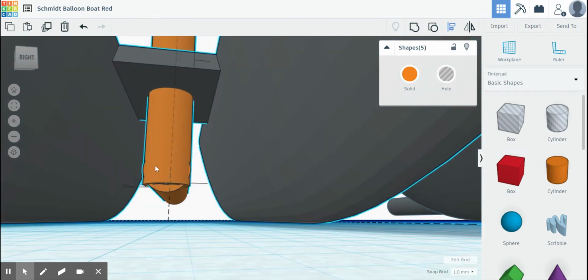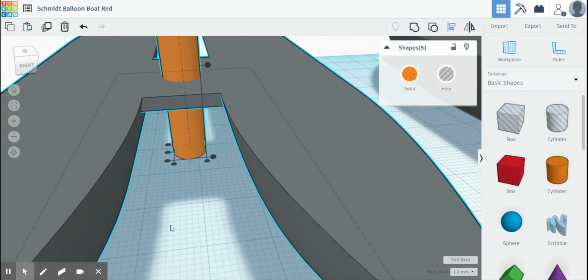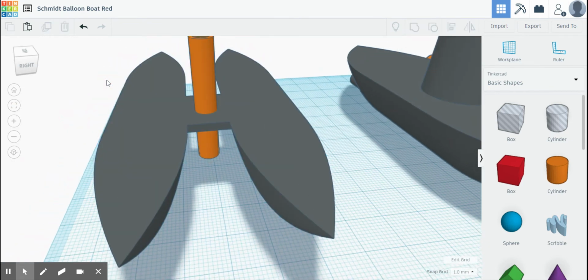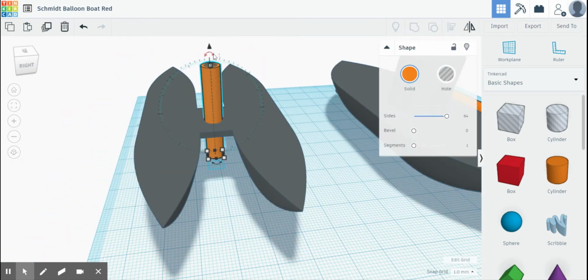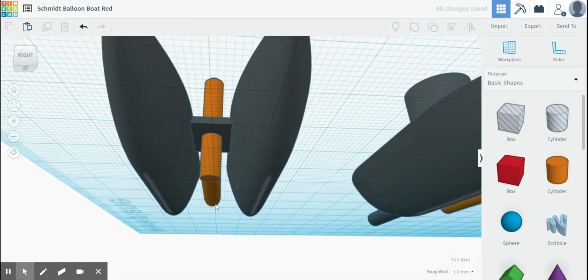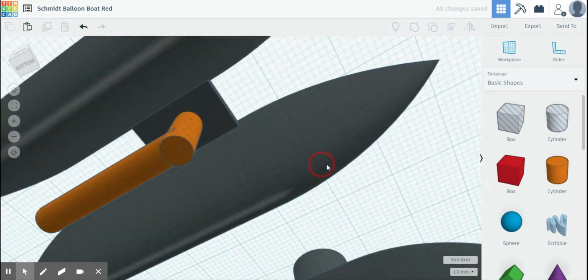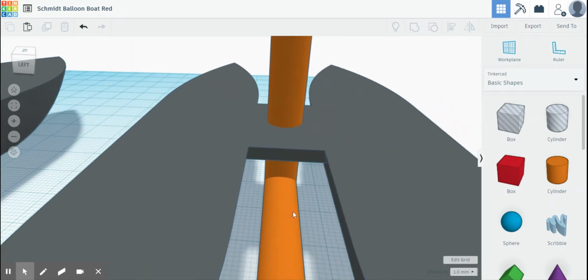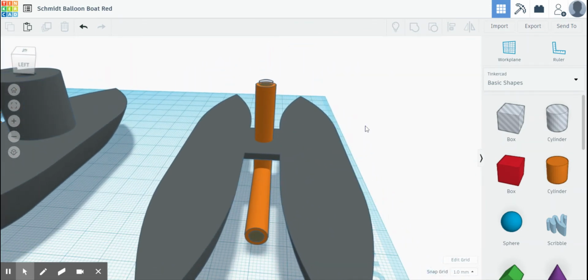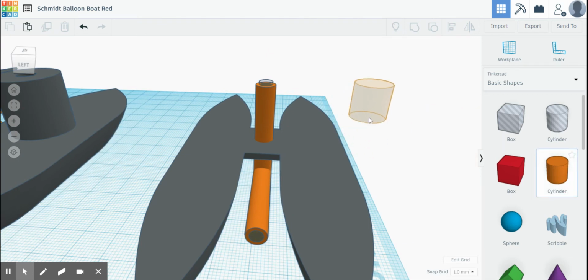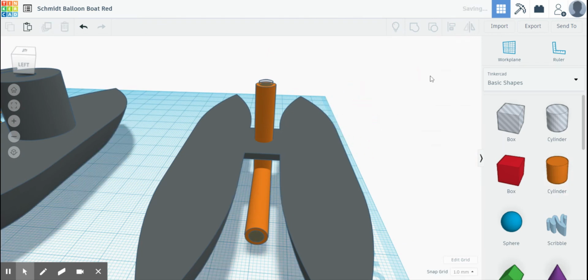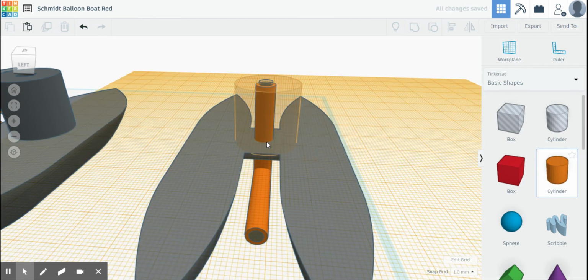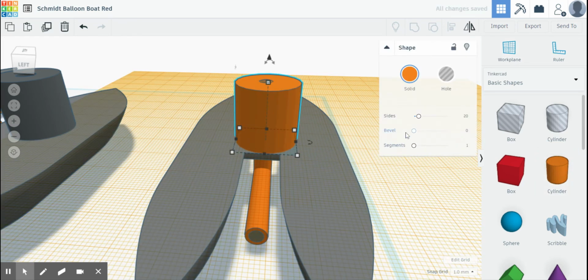And yeah, it looks like I need to bring the outside cylinder down just a little. So I'm going to click off of my objects, click just the outside cylinder, and drop it down 1 millimeter. I zoom back in. All right, looks like everything's touching. That looks really good, actually. All right, then last but not least, I need to put a regular big old cylinder on top. Whoops, remember I want to grab a work plane, put that work plane on top, and bring in a cylinder to set on top for the air to go into.